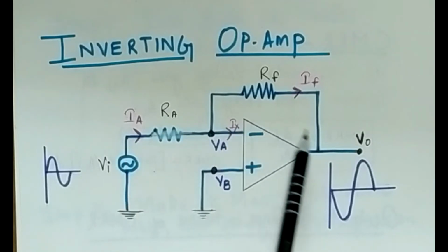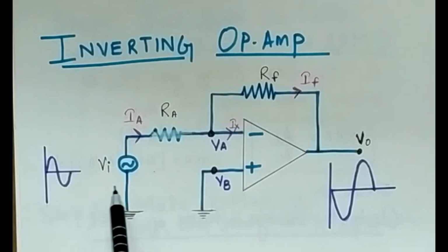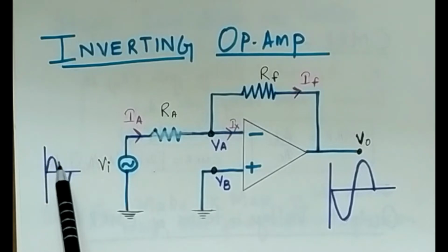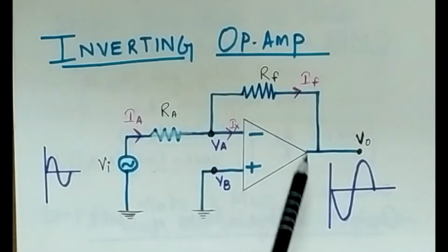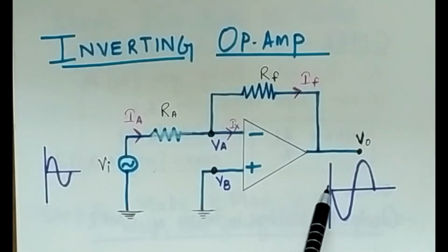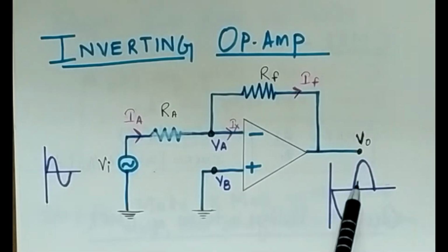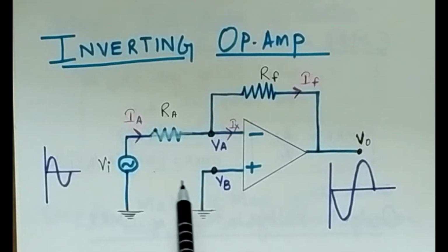called an inverting OPAMP. And another thing is, if you are giving any input signal to the OPAMP, the output will be amplified and will have a 180-degree phase shift, so that is your inverting OPAMP. It has wide application in many areas. It is basically used in oscillators. It is also used in DC amplifiers. So it is a very important topic.